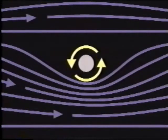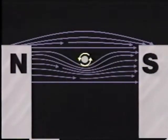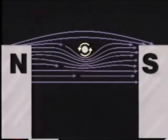The result of this difference in flux line interaction causes the conductor to be pushed by the strengthened field toward the weakened field. The magnetic push continues until the conductor leaves the field of strong flux interaction.